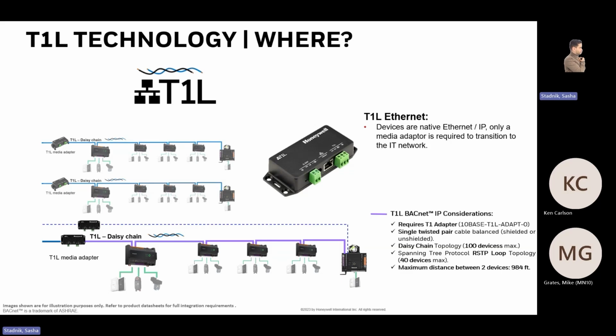In the example we had, the bus was run in a 2-story building, from the corner of the one building, all the way across the building, up the other wall, and then all the way across the top floor of the building. So we had to put a repeater. This was an existing building, we were just retrofitting. So we have a controller that does nothing but get us up to the second floor.